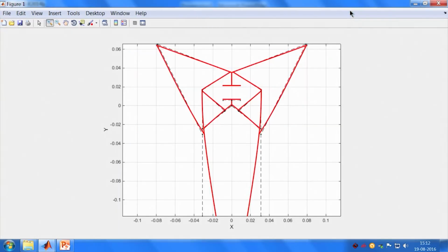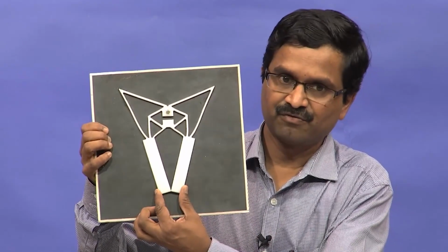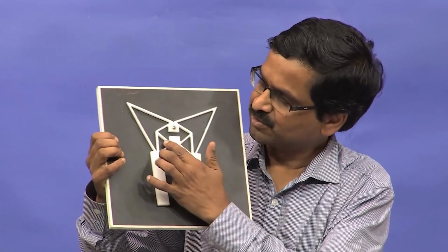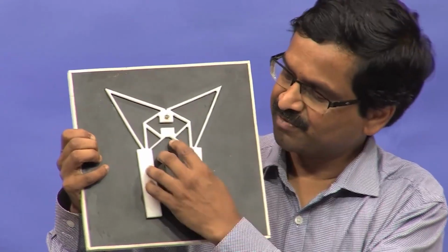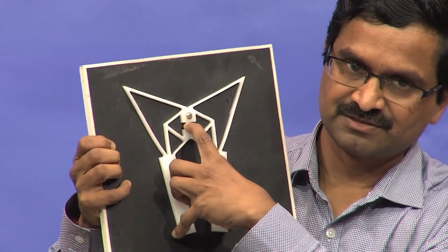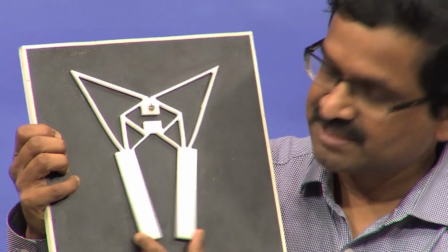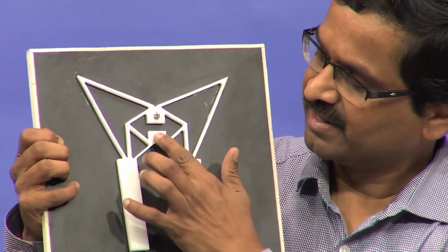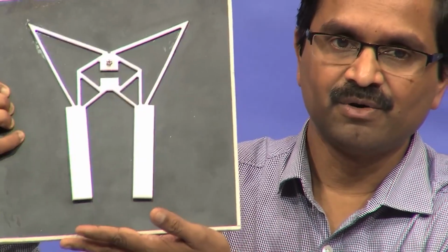That also I have here. It has a thing like this, and when I apply a force, you can see the deformation in MATLAB that we had. When I apply a force, this portion is moving up, right. You can, ever so little, it is a force amplifier. Put your finger here and then do this, you will feel the amplified force. That is why it is displacing a lot at the input and moving a little bit at the output. So, this one, even though it is symmetric, we have modeled the whole mechanism.